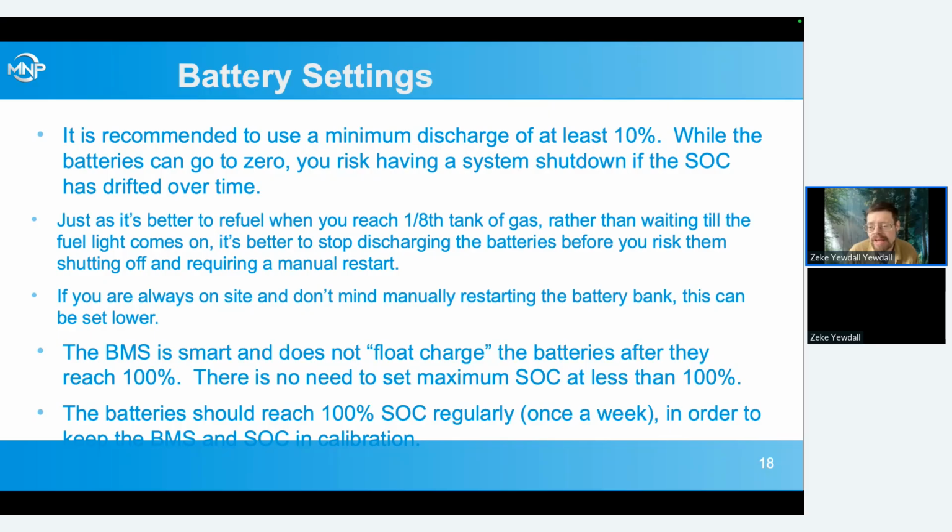So if you have several batteries and a single inverter, just the idle load of the inverter is less than what the battery BMSs can notice. That doesn't mean that they're not slowly discharging, but they'll continue saying 100% SOC if all they're doing is running the inverter in idle, which in a backup power system is the case at nighttime all the time.